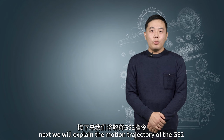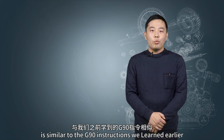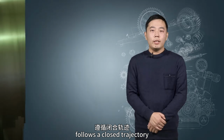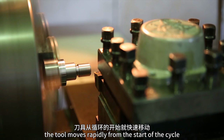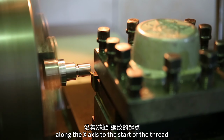Next, we will explain the motion trajectory of the G92 command and the process description. The G92 cutting trajectory is similar to the G90 instructions we learned earlier. Either cylindrical thread cutting or taper thread cutting follows a closed trajectory. The tool moves rapidly from the start of the cycle along the x-axis to the start of the thread.